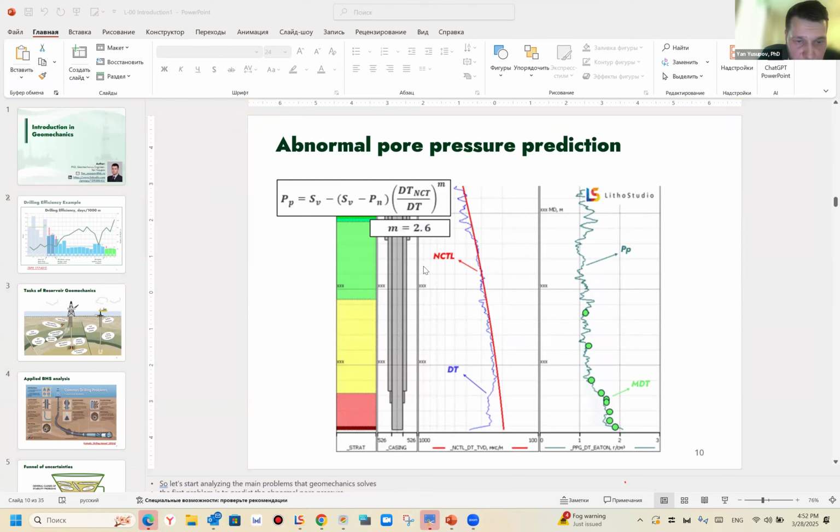What models are you considering for borehole stability? Only elastic and poroelastic and no plastic? Usually we can use elastic failure criteria: Mohr-Coulomb, Drucker-Prager, and other failure criteria. But for example, for unconsolidated formation, for example, Cenomanian in Western Siberia, we can use a plastic formation model because this is a very difficult formation in terms of drilling. And the elastic borehole stability doesn't work in this unconsolidated formation.